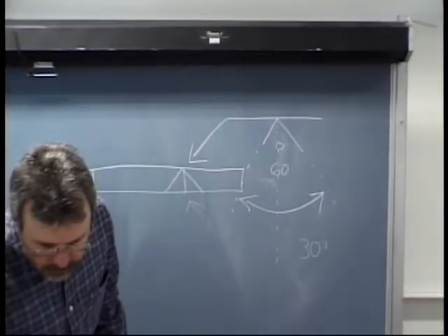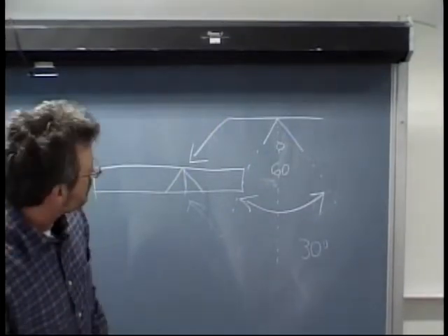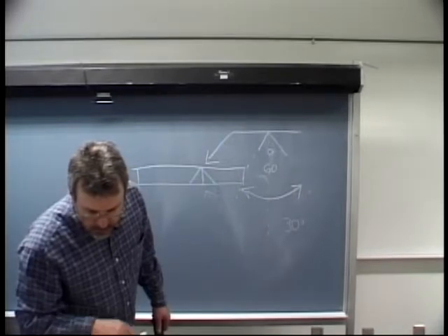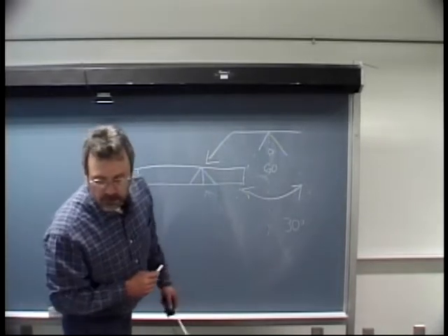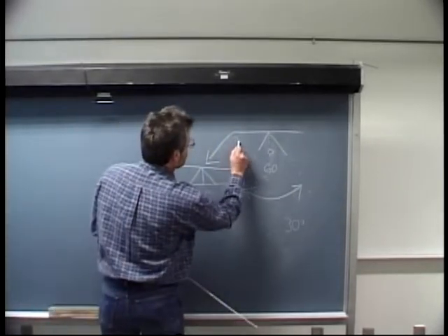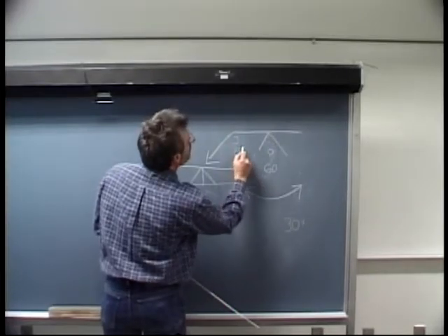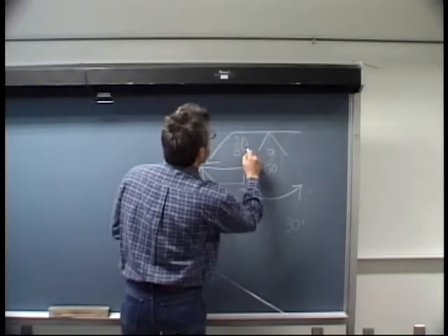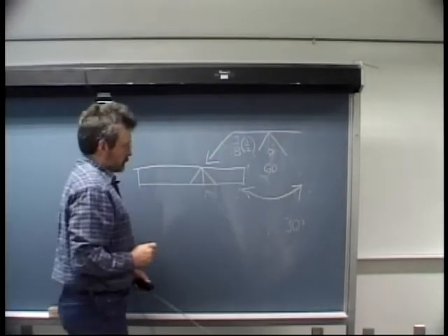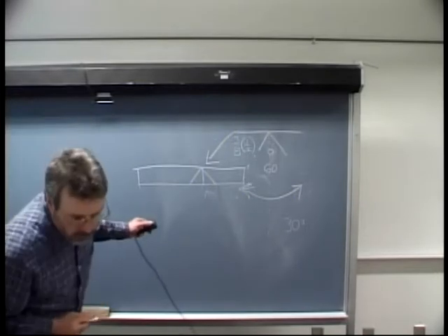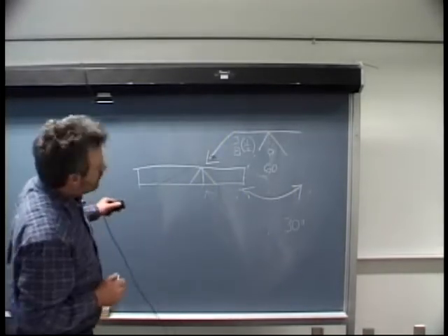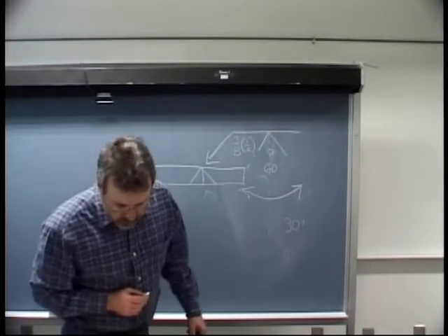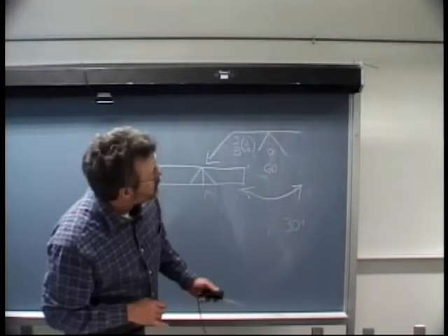So each one of these is beveled at 30 degrees, but the included or overall angle is 60 degrees. And they're showing that the depth of preparation there is 3/8 of an inch, and the groove weld size is 1/2 of an inch. So over here they're giving us depth of preparation, 3/8, and then in parentheses, 1/2, like so. Therefore, we know that they're looking for 1/8 of an inch of penetration into the parent metal. Let's see, what do we have next?